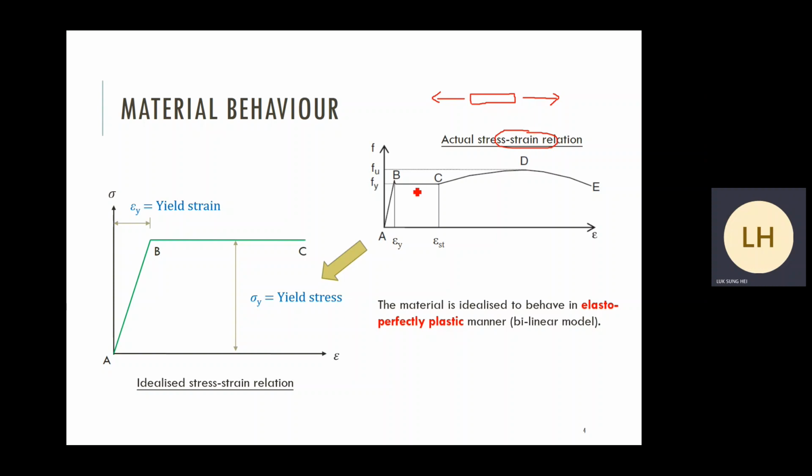The stress strain behavior for mild steel is quite clear because at the beginning you can see the elastic region. And then point B is our elastic limit. Beyond point B, we enter the yield zone, the yield region. For mild steel, you can normally see a very clear yield condition between B and point C. Beyond point C, theoretically, the material enters the hardening stage. Hardening stage means they can take higher stress, higher than the yield stress. Yield stress, we normally use Fy to denote yield stress.